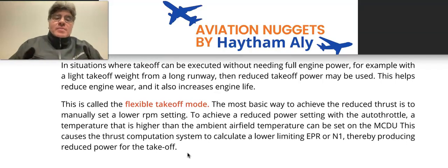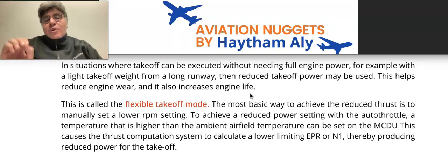So again, the advantage of the flex takeoff mode is that it helps reduce engine wear, also increases engine life and turbine life, and reduces EGT, so that the turbine will not be exposed to a very high temperature like in the normal case of full engine power.